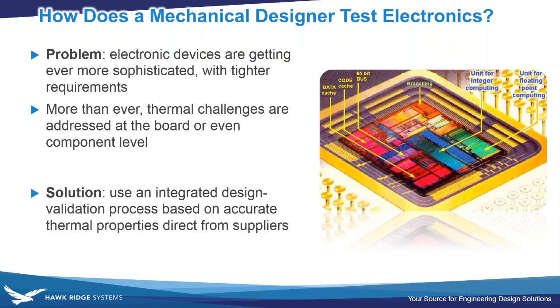While we might be trying to look at some mechanical design changes, such as moving fans around, putting a vent in an enclosure, or designing a heat sink, in a lot of cases whether or not the chip can stay at a proper temperature also depends on how those internals were designed, or other aspects of, let's say, the layers in the PCB, or more sophisticated cooling devices that we might use.